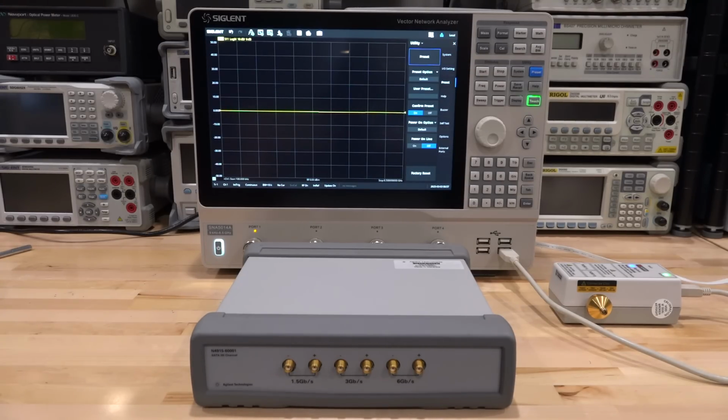Or if you have a frequency based instrument like a vector network analyzer, you can get the frequency response of the channel, and from that you can use the duality of the frequency and time relationship and figure out what the step response of the channel is. And from that you can compute things like eye diagram, which can be really helpful. So this is now a software-based solution that sits on top of something like a vector network analyzer. And of course the Siglent instrument has that option as one of the things you can purchase for it. So let's take a look and see how well it can be used to characterize something.